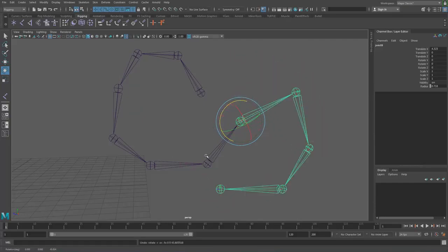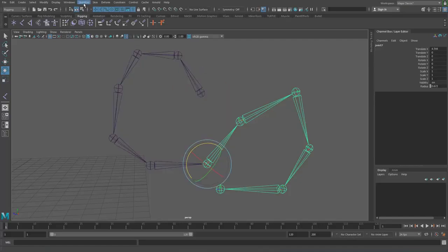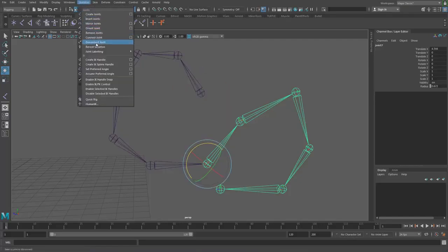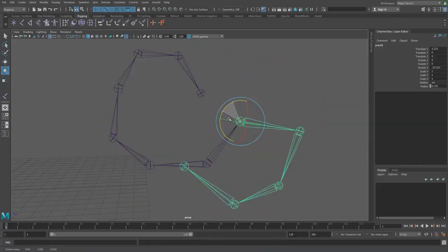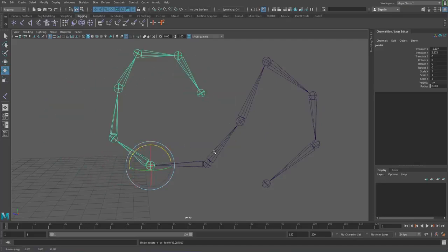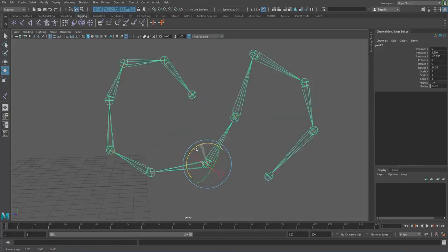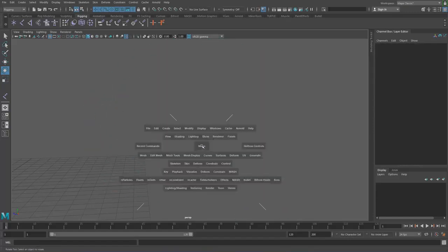Okay, and this one joint that we can select that selects the entire chain is something we call a root joint. At any point we can change that. We can go to skeleton, and there's an option here called reroute skeleton, which now means that it rotates from there, and we've got options here to move that one on its own and that one independently. Depending on the model that you choose, this root joint would be in maybe different places. So anyway, that is how this works.